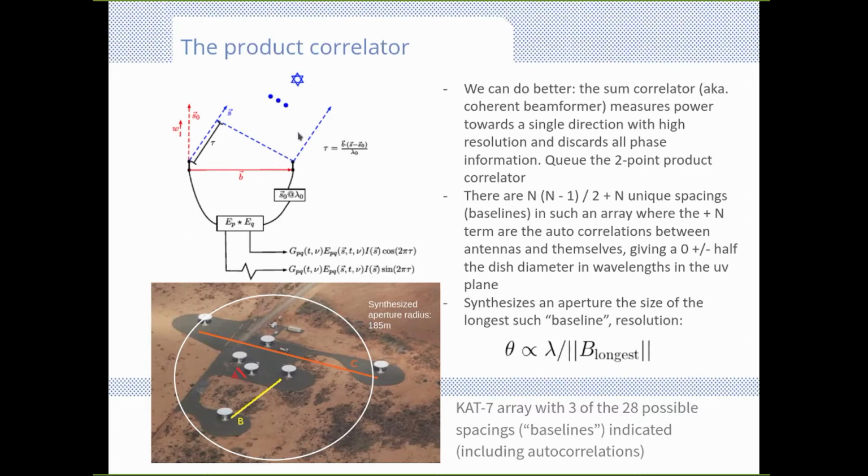And what we're measuring then is the brightness of the source and the delay difference between the wavefront as it's traveling through free space, hitting the first antenna, let's say this antenna over here, and the time taken for that signal to induce the voltage on this antenna here. So that is this delay term. The delay term is just a dot product of the source offset vector.